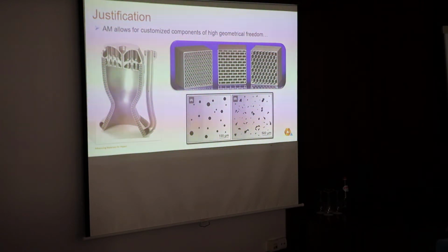intentionally impacted upon our part for some reason or another, as you can see an example here on the left-hand side and also on the top right-hand side, where we have intentionally induced cavities, but also from an unintentional standpoint, whereby we may have process-inherent induced defects in the form of lack of fusion or gas pores.